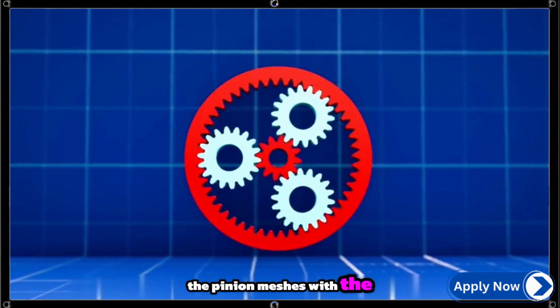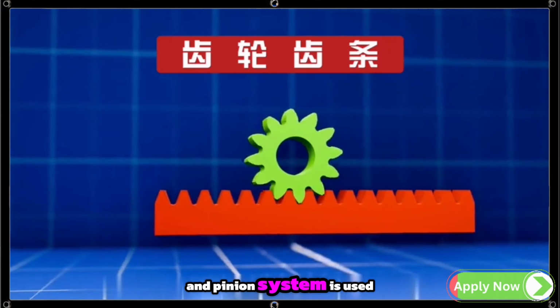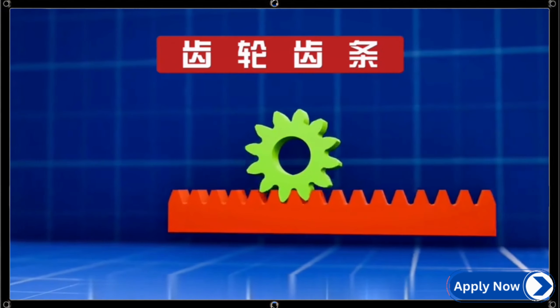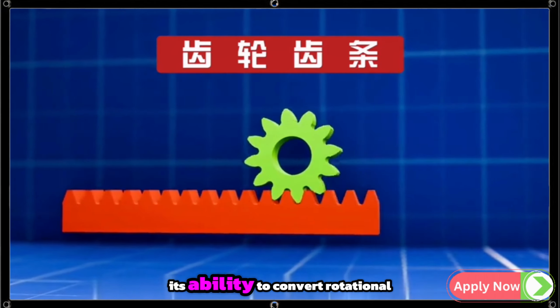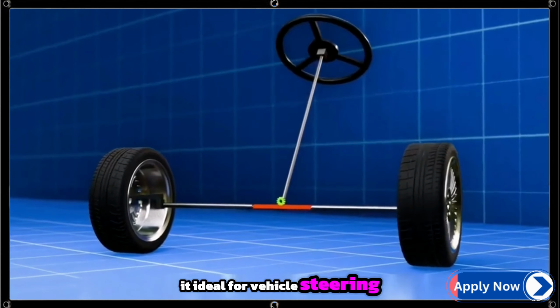The pinion meshes with the rack. Or vice versa, a rack and pinion system is used. It consists of a circular gear, a pinion meshing with a straight tooth rack. When the pinion rotates, it drives the rack, thereby generating linear motion. Its ability to convert rotational motion into linear motion makes it ideal for vehicle steering systems.